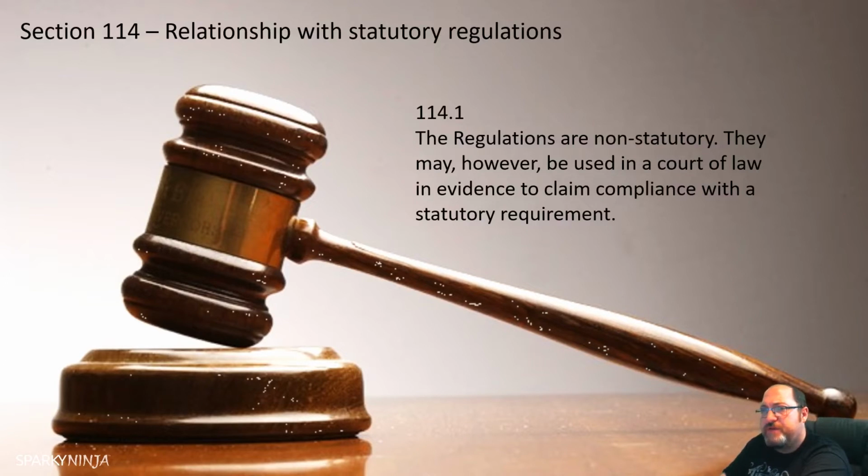Okay, I'm assuming you found that now. If not, I'm not going to say page numbers, 359. But just pause the video if you haven't found it yet. And it just gives us there, in the UK, the following classes of electrical installations are required to comply with the statutory regulations indicated below. Okay, so for distribution, it says the Electricity Safety, Quality and Continuity Regulations, a bit like I just said.